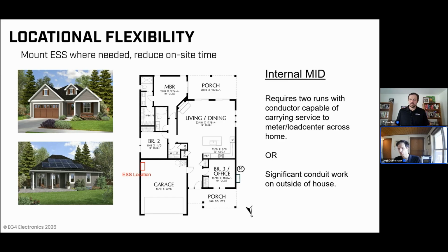But again, you can see in this situation, although your meter and your panel are on the side of the house, that's going to be a very difficult run. This is actually personally how my own home is wired. I will say it took an entire day of labor, because we're talking about either a 2-aught or a 3-aught run, depending on what your AHJ is going to require. A lot of times it's going to be a 2-aught copper cable run in each direction, right, for this entire service. In my house, that was about 60, 70 feet in one direction. That's a lot of copper, that's a lot of conduit.